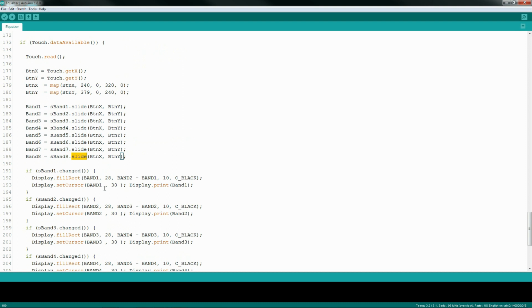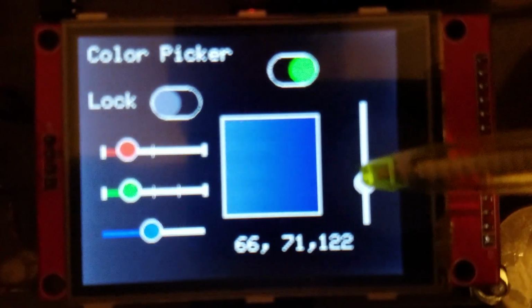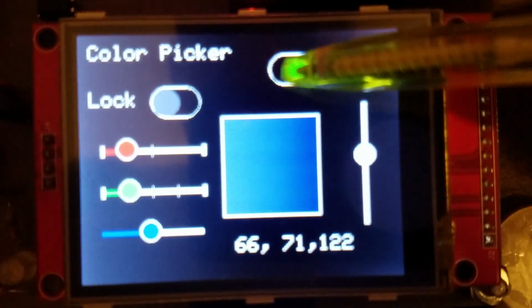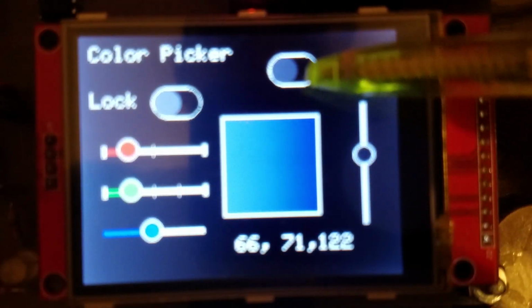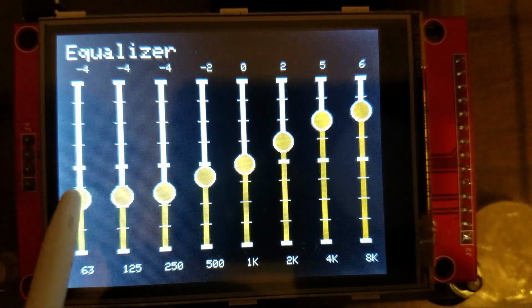If your finger's on a slider, it will return a scale value somewhere between your lower and upper limits set in the init call. Then process the callback accordingly. Maybe you can set an RGB value, maybe you want to specify a motor position, maybe set a timer delay. The sky's the limit. This code is pretty small and snappy, as you can see.